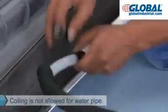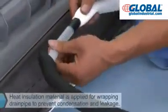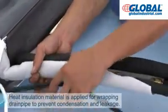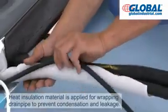Cooling is not allowed for the water pipe. Heat insulation material should be applied for wrapping the indoor side of the drain pipe to avoid condensation and leakage.